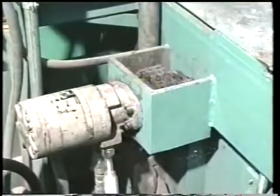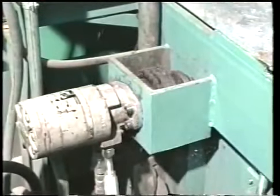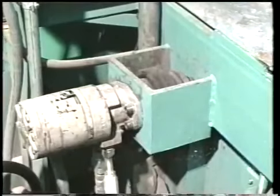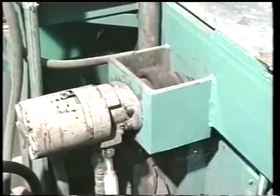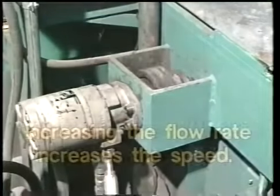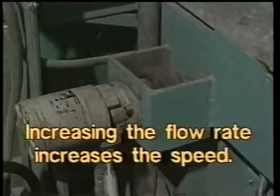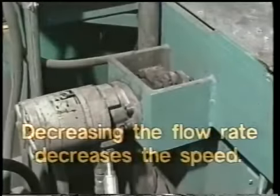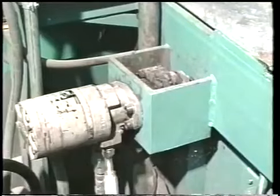If flow through the motor increases, then the vanes will turn faster, and the speed of the shaft will increase. Again, this direct relationship between flow rate and speed is the same for all hydraulic motors. Increasing the flow rate will increase the speed, and decreasing the flow will decrease the speed, as long as the size of the motor remains the same.